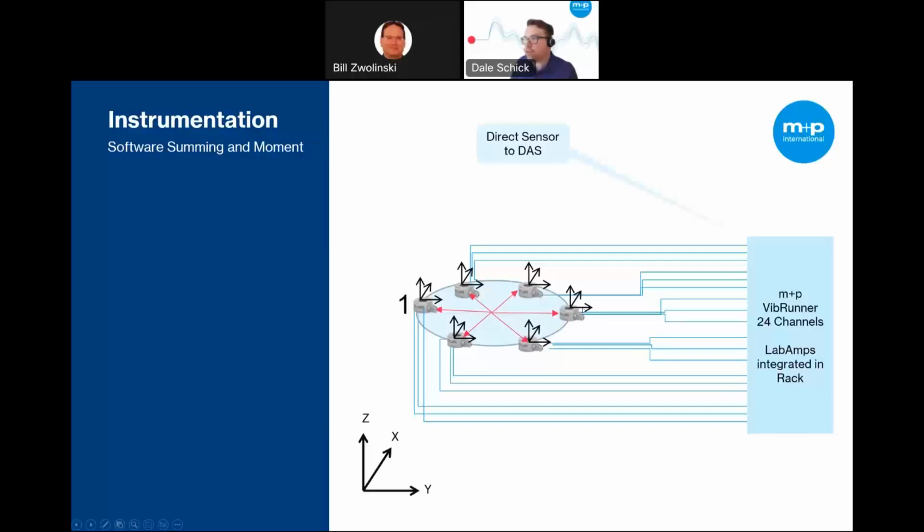So if the vector of motion is directly in line with what would be the y-axis on this system, but the CG were slightly off, we would still calculate and limit to that somewhat off-axis center of gravity. Whereas if we had summed the pairs to calculate the moment, we might only see the in-axis energy, and it might obviate anything that's off-axis.